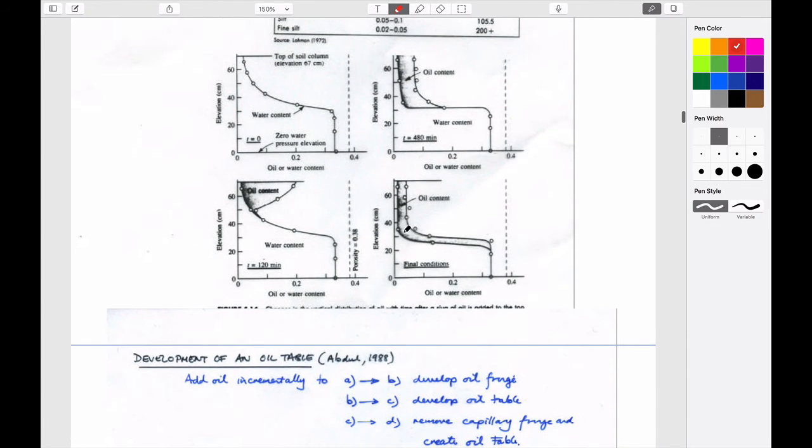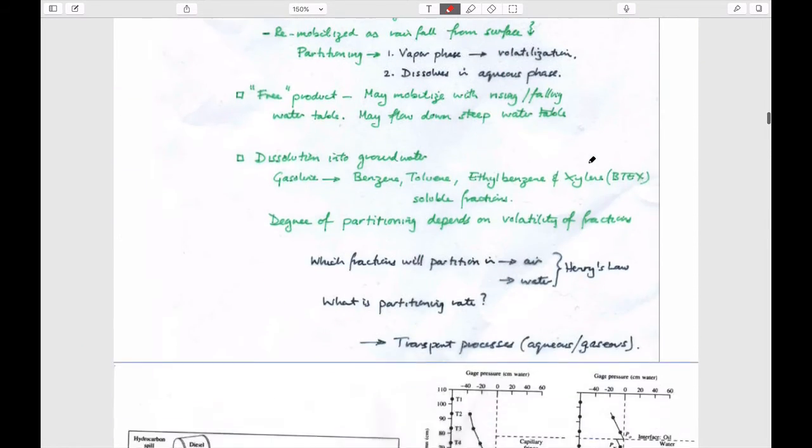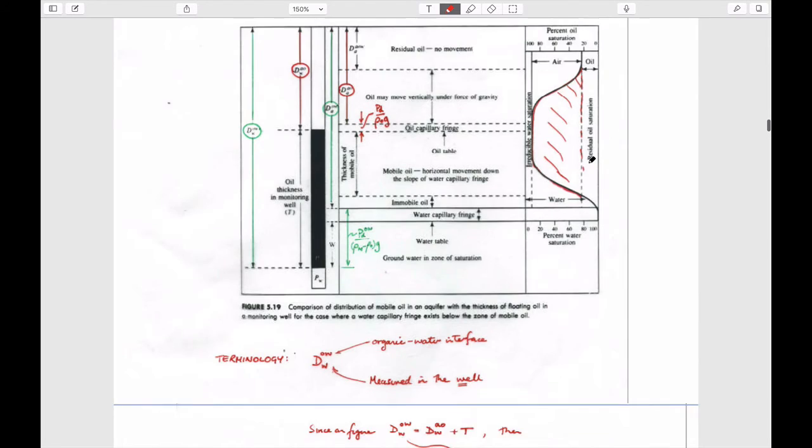And to be able to describe exactly what this was: this is the water table, this is the lens that sits on the water table and slightly depresses the water table, and then this is the chimney above it, which has a relatively low saturation of the NAPL. So that's, again, an important concept. So if you have those, you can do a lot with the stuff that we talked about in this class.